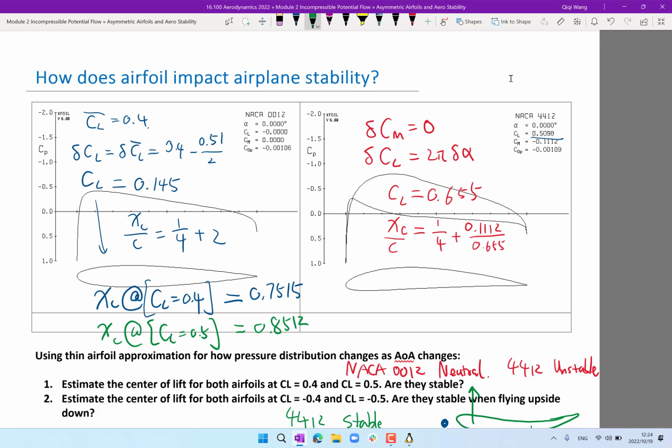Yeah, so that's actually a very good way to think about the average aerodynamic center, the average quarter chord. It's not a quarter from the leading edge of the first wing to the trailing edge of the last wing. It is taking each individual wing, looking at the aerodynamic center of each, and then averaging them weighted by the area of the wings, because that's how strong these flat plate solutions are.